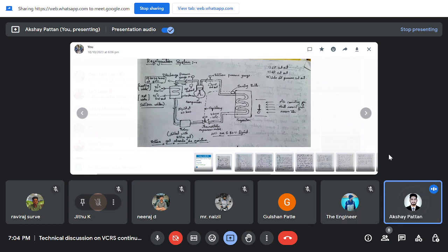Okay. So why is there a low pressure at the suction side of the compressor? Why are the low pressures achieved? So that the low pressure cutout cuts out, and it is actually a compressor safety device. It is used to prevent damage to the compressor. So what are the factors affecting the low pressure?